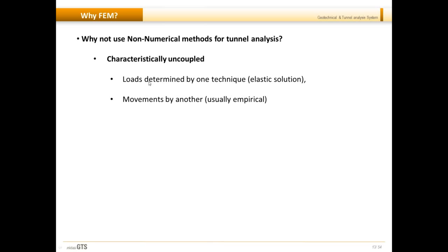Between the loads obtained from your structural analysis, let's say, and the movements obtained from your empirical formula, there is a physical mismatch. Therefore this type of analysis or methodology would not only lead to a conservative design, but sometimes it might cause complications in your actual project during construction.